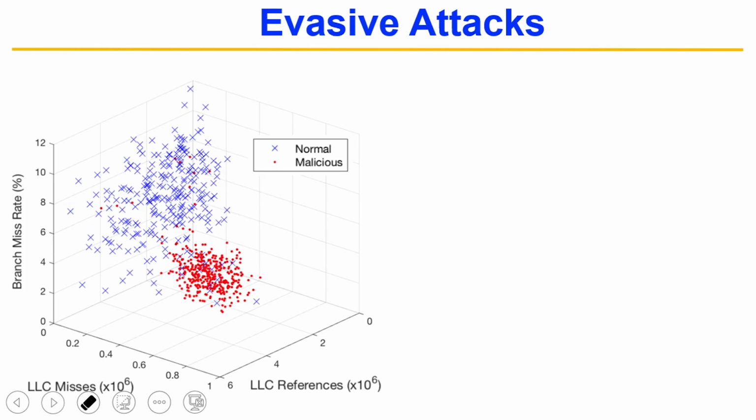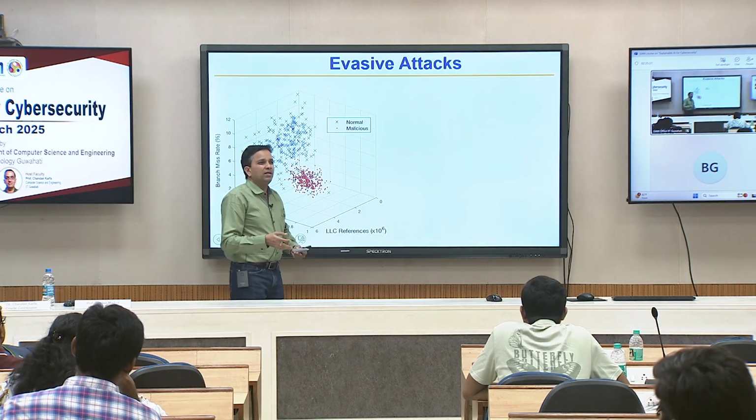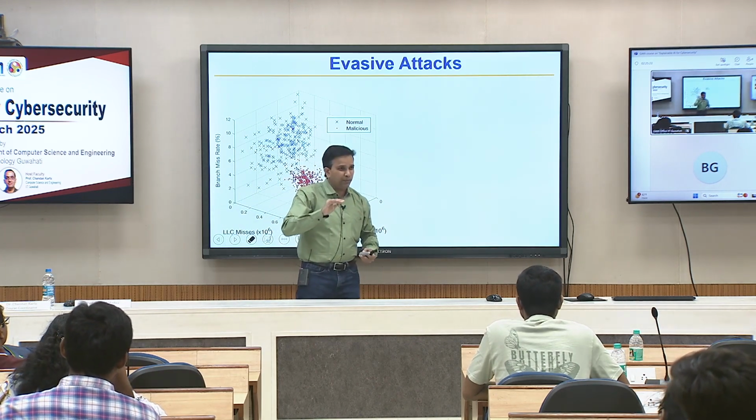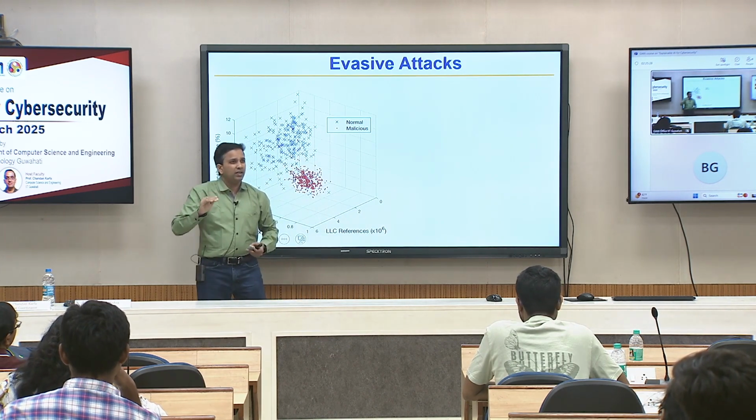Now, does anybody remember where these features come from? Every processor comes with hundreds or 200s of performance counters, where it computes and maintains what is going on. If you executed a program for 1,000,000 cycles, you can know how many of them are add instructions, whatever question you want to ask, pretty much they maintain all of them or most of them. How many branch instructions, how many of the branches were mispredicted, up to that point. You can stop anywhere, start anywhere, reset anywhere, restart anywhere.